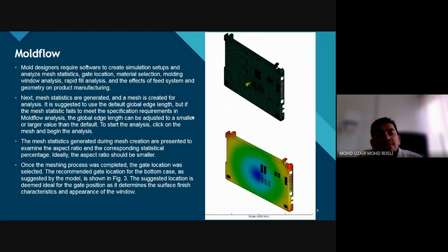Then mesh entities are generated, and a mesh is created for analysis. It is suggested to use the default global edge length, but if the mesh fails to meet the specification requirement in Moldflow analysis, the global edge length can be adjusted to a smaller or larger value than the default.